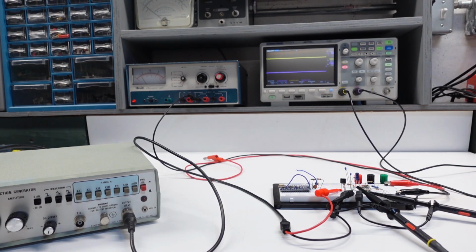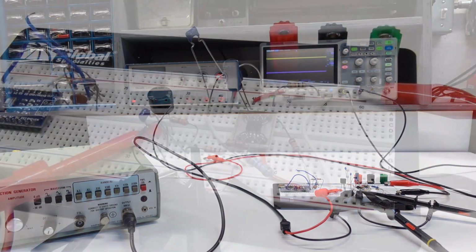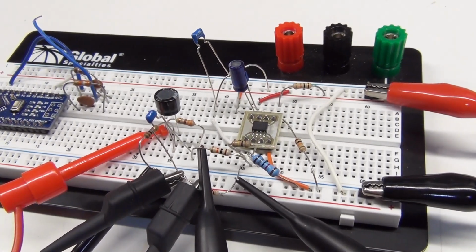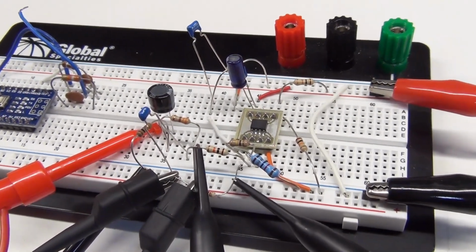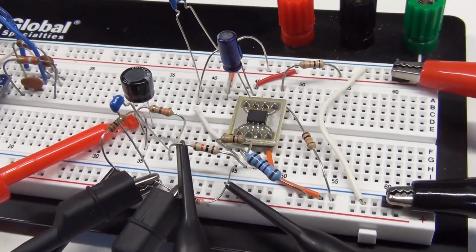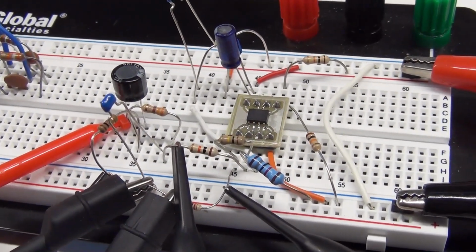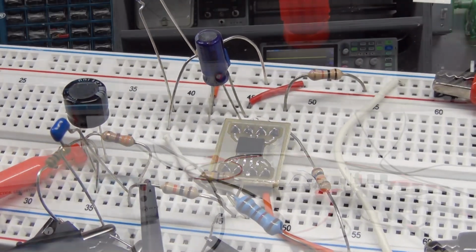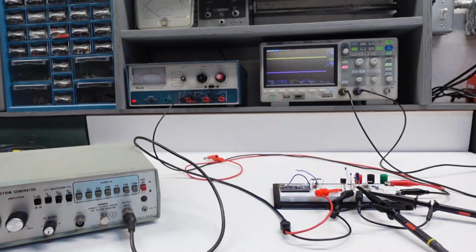Okay, I've got this circuit built up and connected, and I'll do a little zoom in here on the breadboard so we can take a closer look at the circuit. Now, there's really not that much to it, and this is low enough frequency that I can do a breadboard. And the only little trick I had to do here is I whipped up my own little SMD adapter so I could put that little SOIC8 package on a piece of board with pins on it so I could put it on the breadboard, and so that worked out fine.